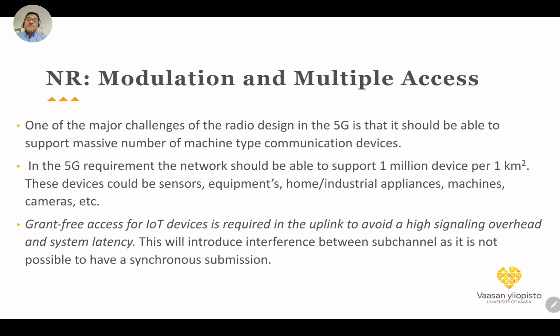So in 5G, in order to minimize the latency, we should provide grant-free access. So the IoT or the sensor device should transmit the data whenever there is an event that they need to submit, without requesting access to the network and spending a long time to set up the access. As we saw before, the control latency can be up to 10 milliseconds. So if every time the sensor wants to establish a connection to the network, they will lose 10 milliseconds every time. So in order to handle this problem, we should have grant-free access, so the IoT can transmit whenever they have data.